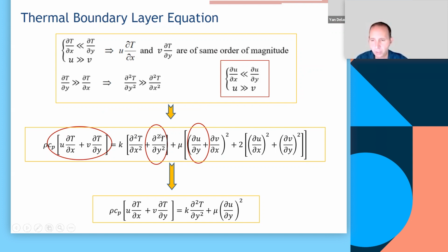So what are they? It's a little bit more complicated than some of the others because we've got something called a viscous heating term. And the viscous heating term is essentially a transfer of mechanical energy to thermal energy through viscous dissipation. So if you rub two fluids together very intensely, you generate heat in there. So looking at the overall energy conservation equation, we have the convective transport, the diffusive transport, and the heat dissipation.